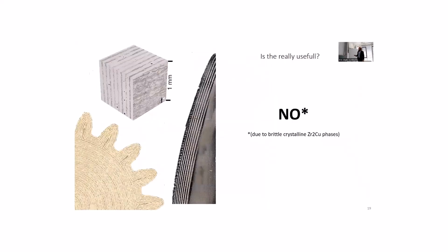At the end, is it any good? No, because the phase that we are getting, the paint we obtained, is actually bad. It's kind of gray, brown, it's poor paint for us, because the phases we are getting in here are brittle. And my PhD was about ductilization of BMGs via introducing phases there. While they were brittle, it was okay, the effect was there, but not really a big one.